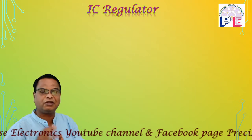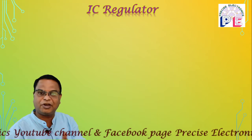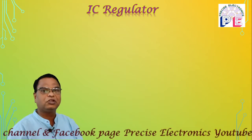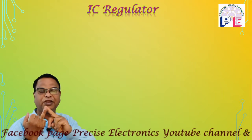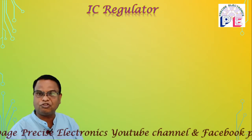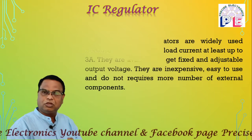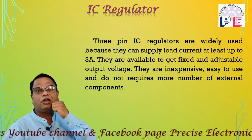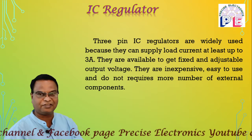In a fixed regulator, the second pin is known as the common pin, while in an adjustable regulator, that pin is known as the adjustable pin. And the next pin is the output terminal. That means one pin is used as the input terminal, one pin is common, and the other pin delivers the regulated DC potential. As there are only 3 pins, the external components used are fewer in number, so obviously the cost of that power supply decreases.